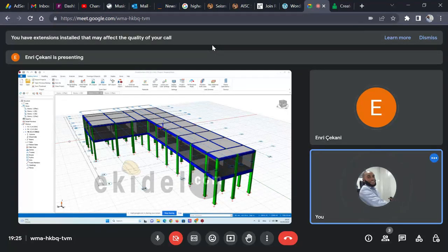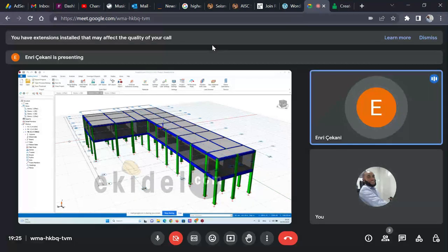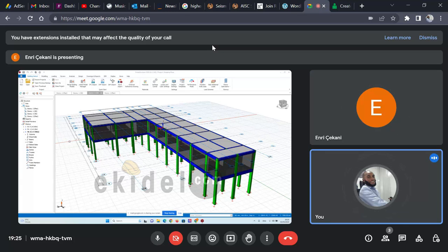Now, this first one is mostly not considered, because you cannot have, let me say, a 10-story building in an earthquake zone and then go and reduce the weight of the structure, which has its own self weight. There is no way you can totally reduce the weight of the structure to avoid the loss of ductility. So the only way to do that is to use the second option, which is to increase the strength and ultimate deformation.